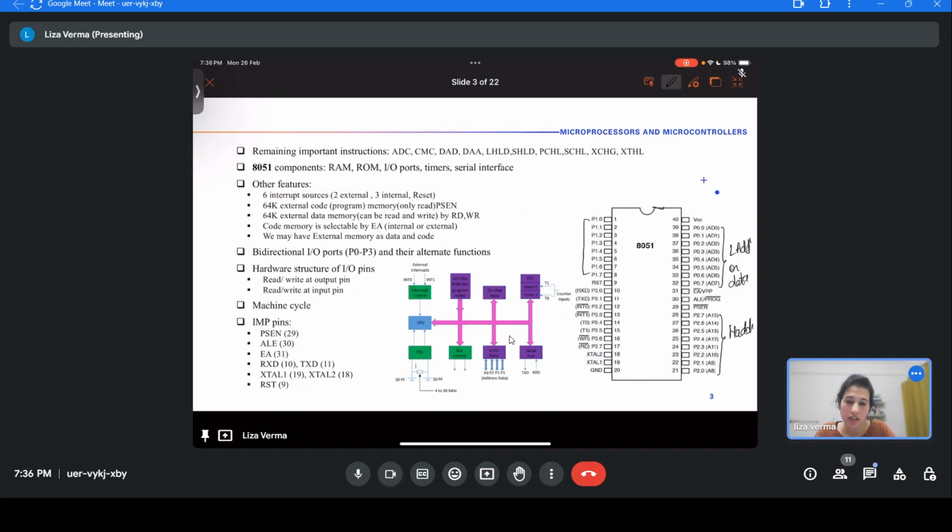It must be 07. I know that doing microprocessor and microcontroller in one course is going to confuse you, but you need to get this clear: the stack pointer's address is 07 and not 0007. I think I should have added a memory diagram, but I don't even have it in my notes right now. Should I add it right now, or do you understand why it shouldn't be 0007?